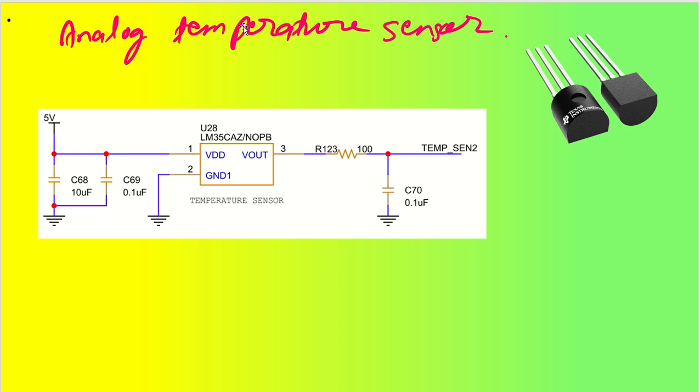One more application circuit for analog temperature sensors can be with the LM35, which is the most popular IC for temperature measurement for various applications, let us say thermometers and other temperature measurements on the board. Let us say we have a 5-volt input as the power supply of the temperature sensor, and the output will go to your ADC pin. So I hope you are now able to understand and realize the importance of the ADC pin, which has versatile applications in various locations in your circuit.